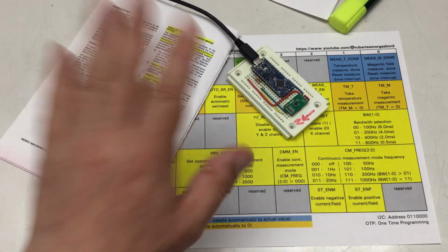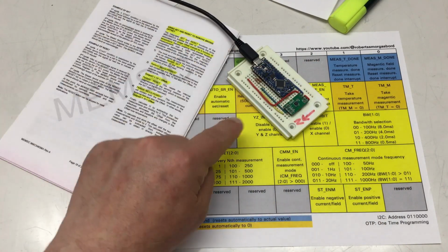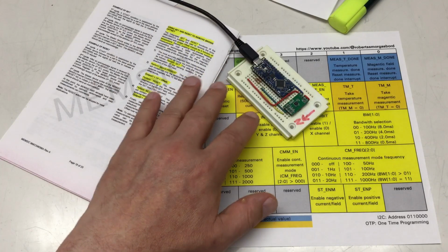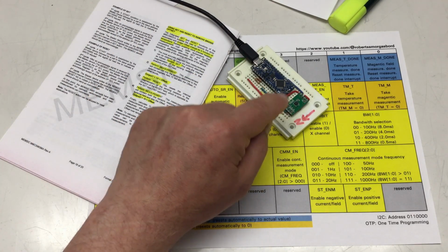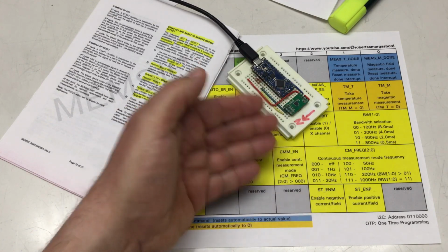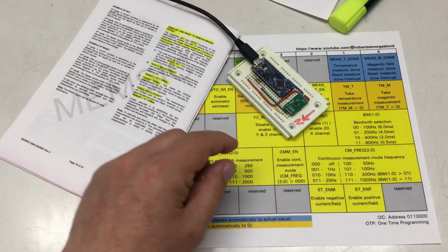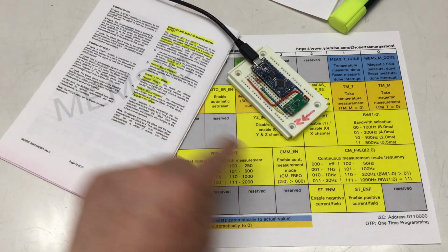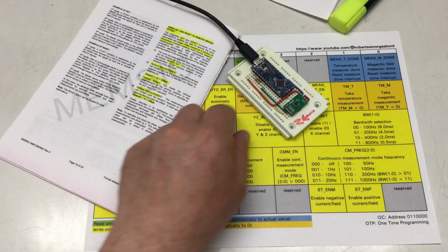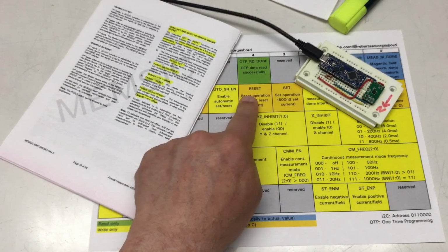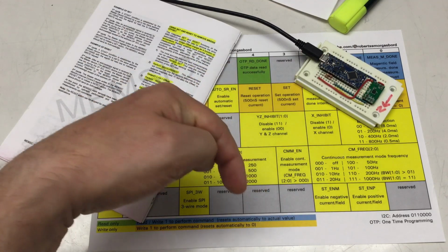In the last video we covered the few remaining bits in the control registers that are responsible for either automatically or periodically setting the magnetization of the AMR sensors in that thing. And we also started to have a look at the AMR Wheatstone bridge offsets that thing can actually measure using its set and reset operation. Card here, link in the description.